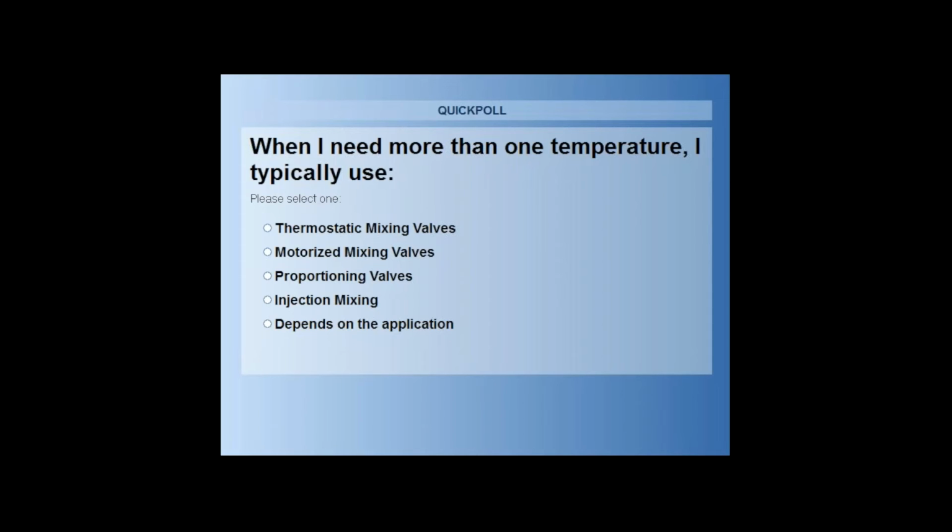One thing, if I could throw in there, Jody, is when using thermostatic mixing valves, just be aware of the CV of the valve. If you buy an off-the-shelf thermostatic mixing valve and try to use it in a radiant application, be aware they're typically a fairly low CV valve. The ones that Caleffi offers are built specifically for radiant mixing, with much higher CV, and that's why you see those in our manifold mixing stations and other places. It's a higher flow valve than your typical off-the-shelf thermostatic valve.